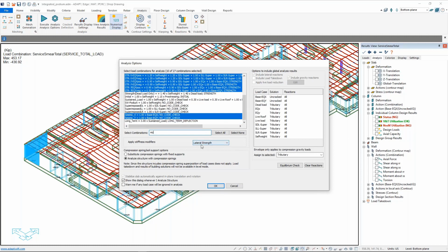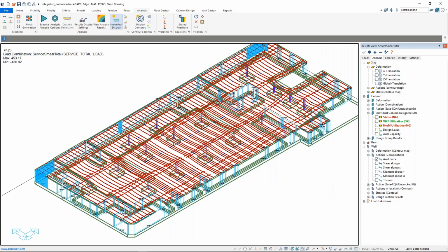I would run that under lateral strength. That means that the reactions in the walls and columns will be based on my reduced stiffness. If you remember when we did the mat, I would then say, oh yes, I remember my EQX should really be coming from this lateral strength, not from my uncracked, which I'm using for gravity. So I hope that addresses that question of how to handle the assignment of cracking for the shear walls.